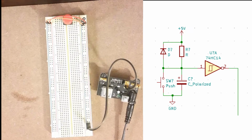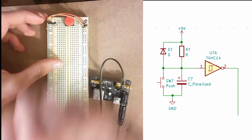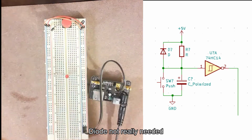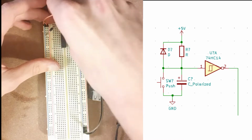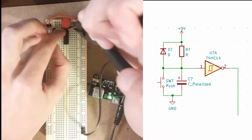At the core of the reset circuit is a capacitor and a resistor. When power is applied, the capacitor slowly charges up through the resistor. When the capacitor voltage is high enough, it triggers a Schmitt trigger inverter to turn off. This creates a short high pulse on startup, whose length is determined by the RC constant. A button also allows the user to reset the circuit manually.